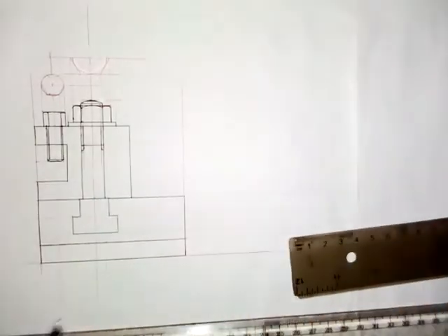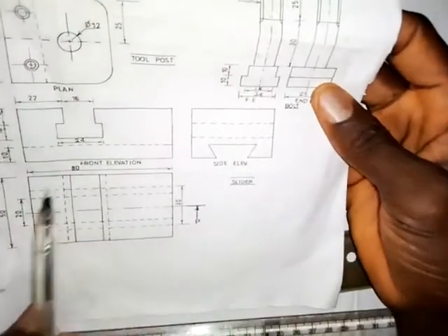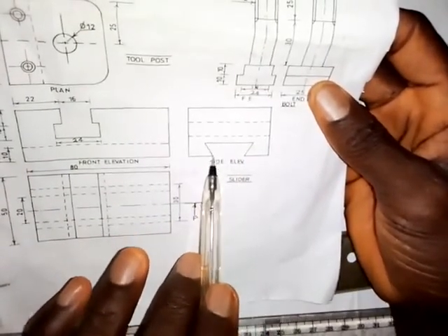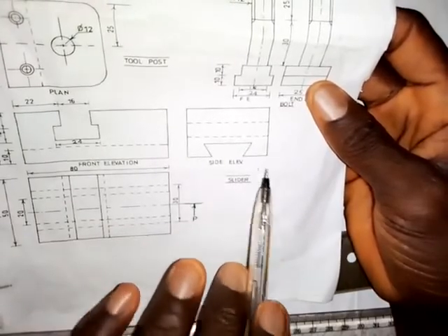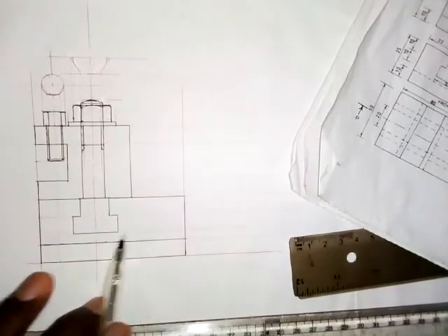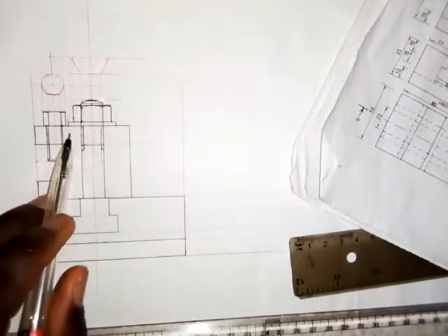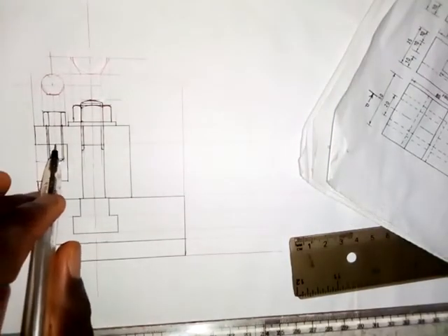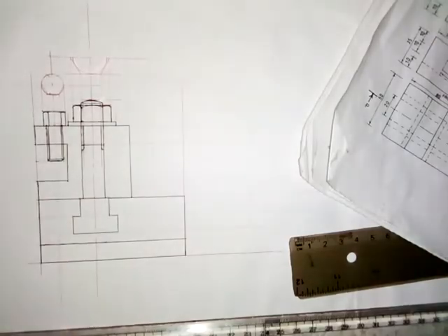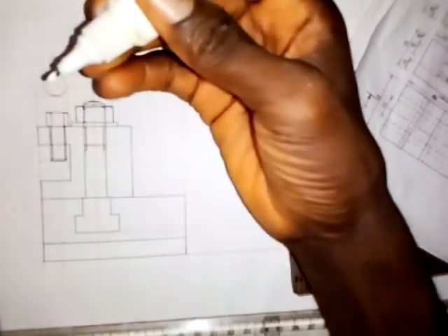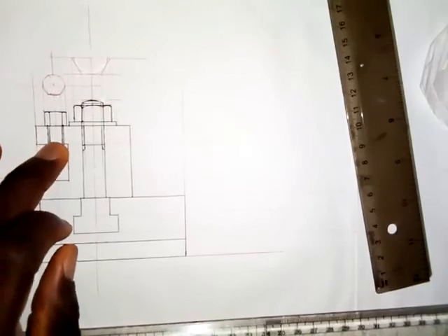So that's it. And then this surface will be plain. You can see that the cutting plane, I said we cut like this, so the cutting plane will not touch this part. This part will remain as it is. It will remain plain, so we are going to leave it plain like this. So this is the solid part. We are going to arch this solid part. Also, we are going to arch this solid part. This line will not be there again, so I'm going to remove this line now. I've removed that line.